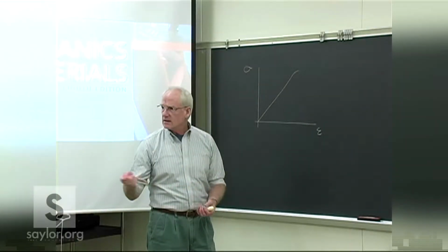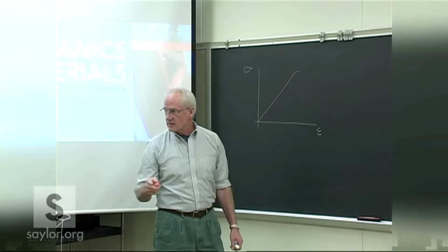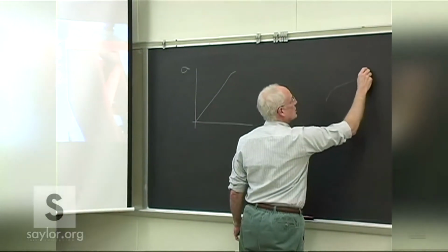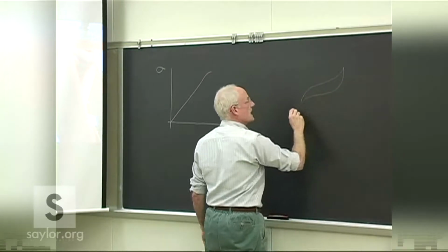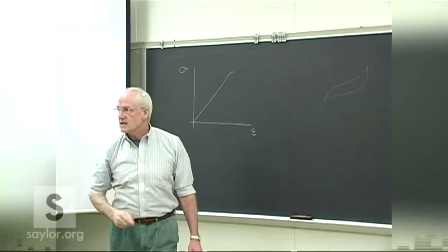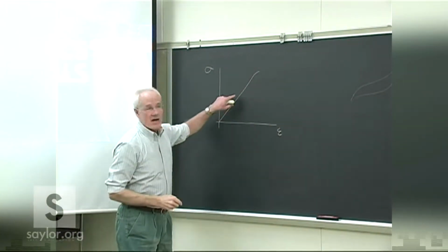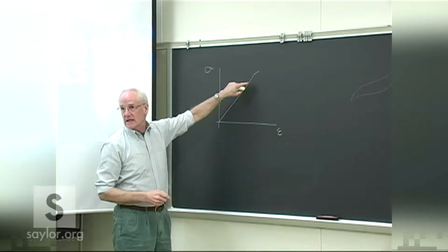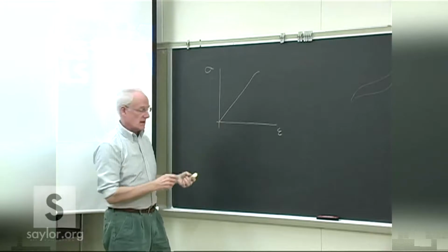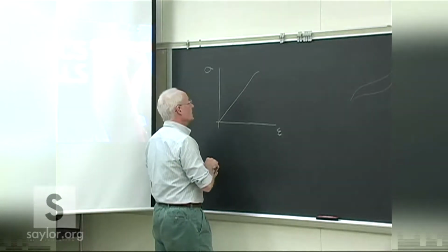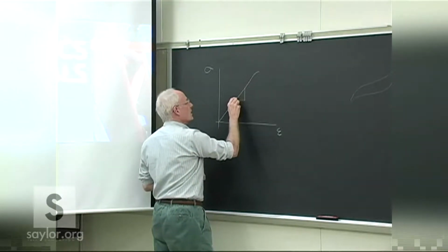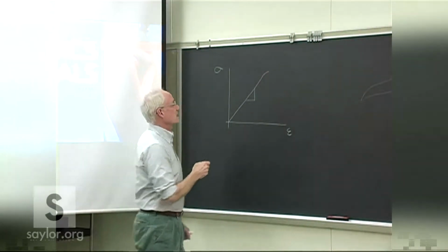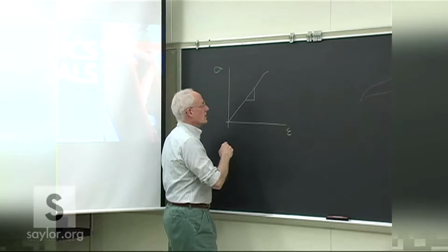I think some of you are in circuits or something, and might have looked at hysteresis. Hysteresis is any curve that goes one way up and comes another way down, and then might retrace that shape again. We do not have hysteresis in this region. We go up this line, relieve the load, come right back down this line. That means it's very, very predictable, and the slope itself is a characteristic of the material, whether loaded or unloaded.